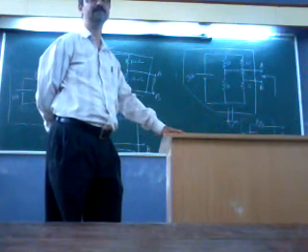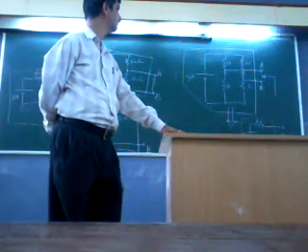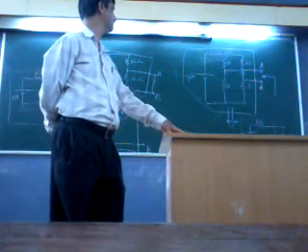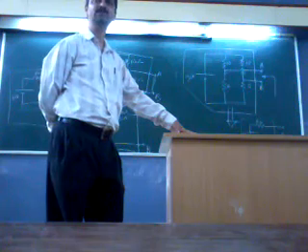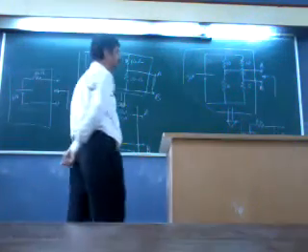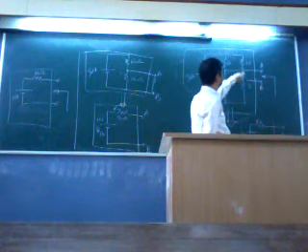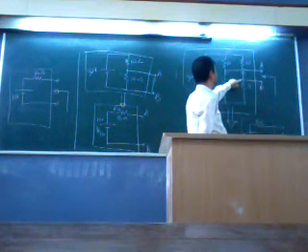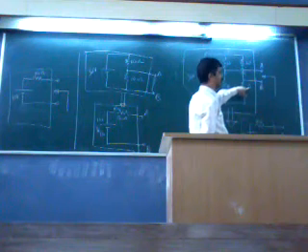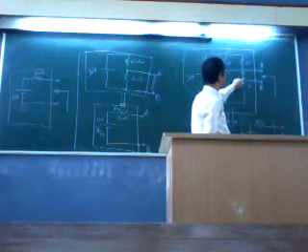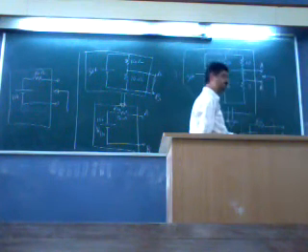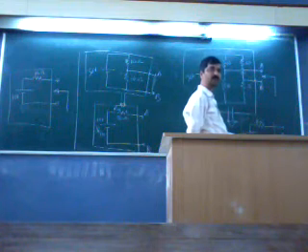RTH you will find difficult. What is VTH? VTH is 5 volts, right? Because for open circuit, what is VA? 50. What is VB? VB is 10 and 5, so one third of 15, and 10, so it is 5. So this must be 5 volts.